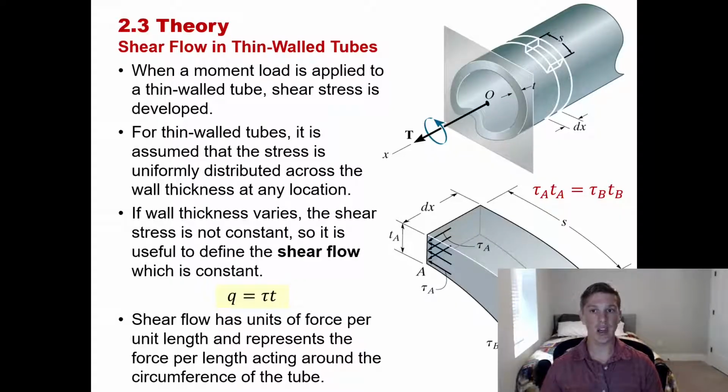I'd probably lean more heavily into doing finite element analysis, or the finite element method, to get a more holistic view of what the stresses are actually doing in the shaft. But this is a really good first pass, and if we're going to have large safety factors, then it's probably acceptable to oversize or over-engineer a shaft if the cost of materials or the weight is not important in our design.